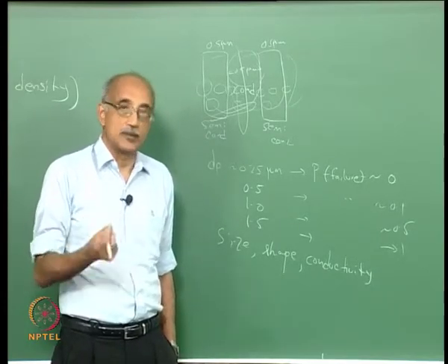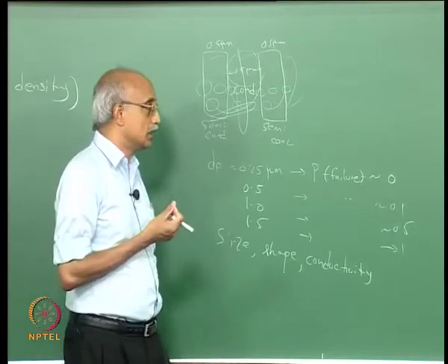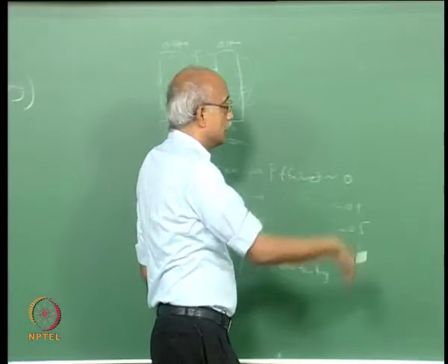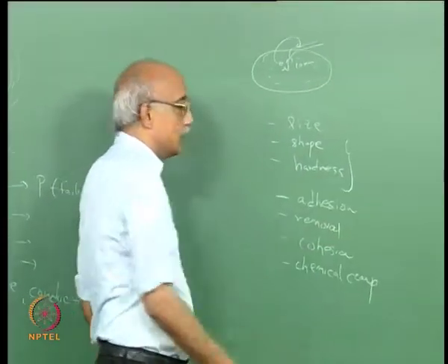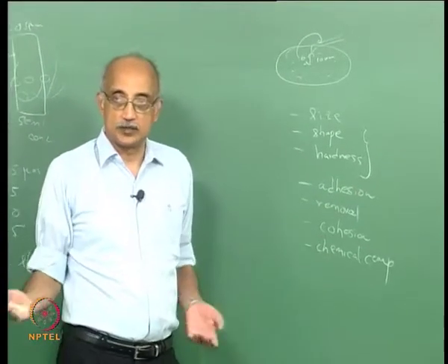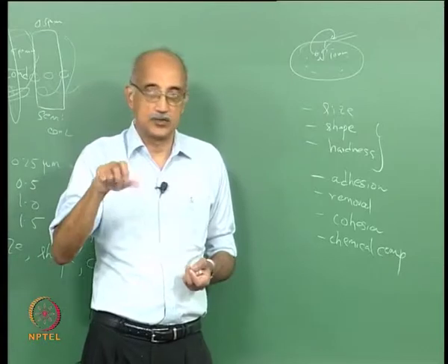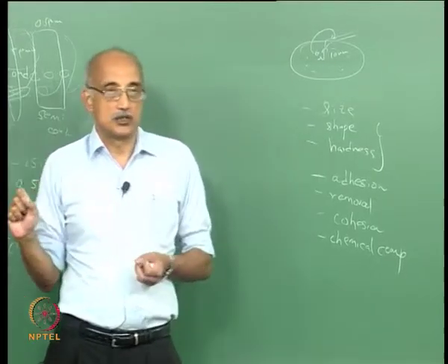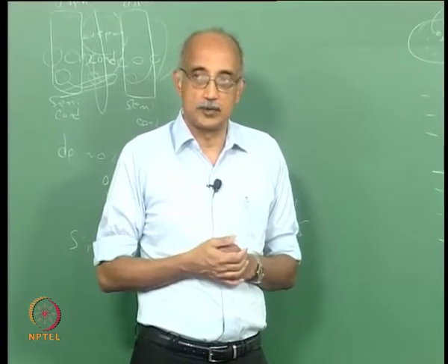They can actually accommodate a very large number of particles and still function quite reliably. And similarly, here if a particle just happens to be somewhere on the outside of the disk surface, there's usually a band around the outer diameter which is not used for data storage. So if particles happen to land in that non-critical location, they don't cause any problems.